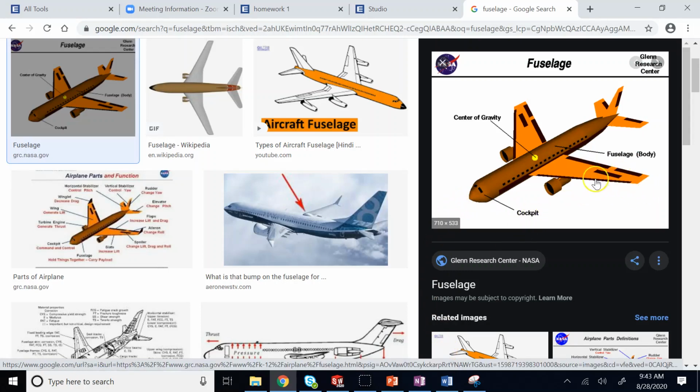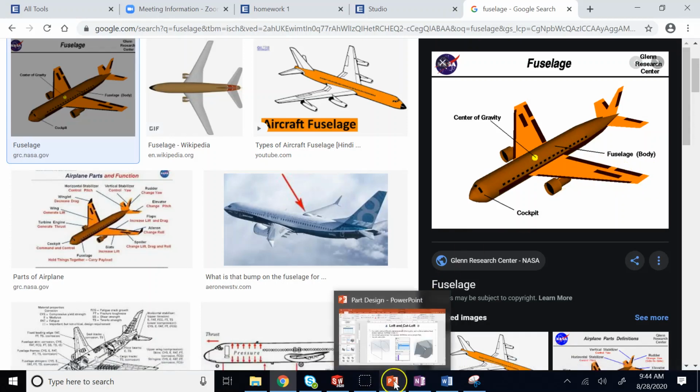The wing itself, the profile, the splines that you have here, I mentioned that the airfoil is a couple of splines, one on the top, one on the bottom. The airfoil that you have here at the tip of the wing is different than the one at the root of the wing. Different sizes. So here you have to have one profile here, one profile there, and then connect them with this loft method. So there are lots of things.